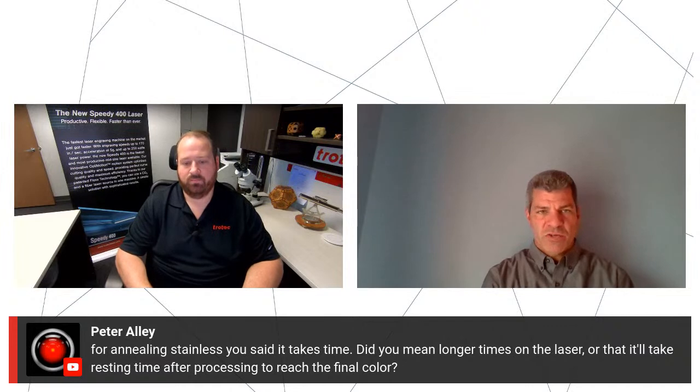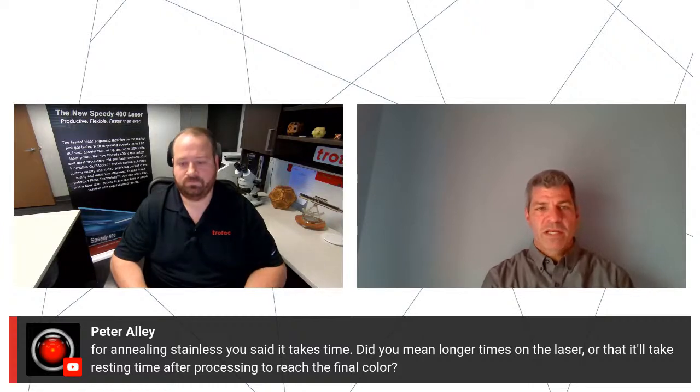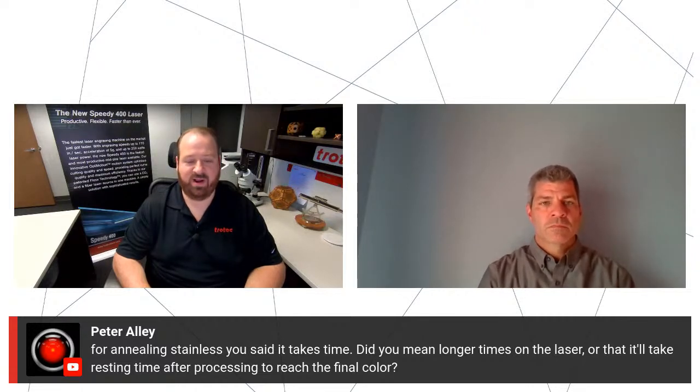It can heat the material up considerably, so you would want to be careful once you've done an annealing, especially if it's a thinner material. When you pull it from the laser, just be careful. It may still be warm, but the result is immediate as soon as the laser engraving is complete. Yeah, agreed. The main reason it does take longer is because we usually have to run at a higher resolution to build up that heat. And so that's where the time comes.